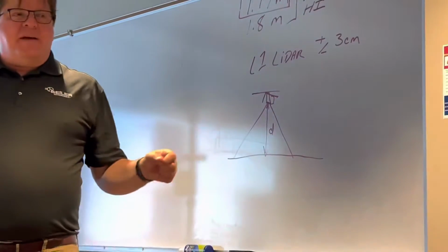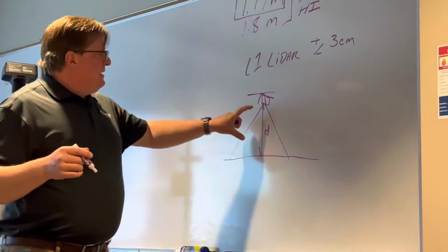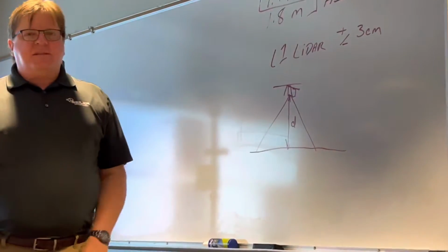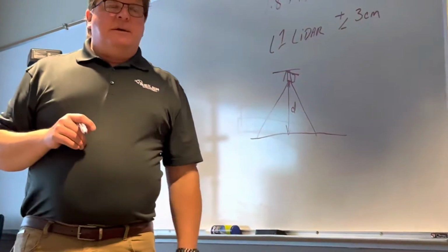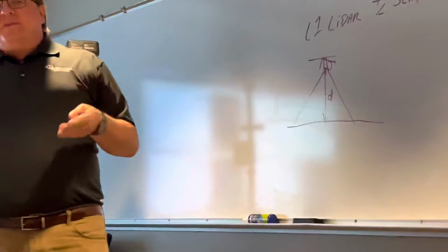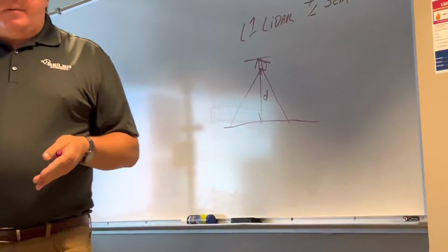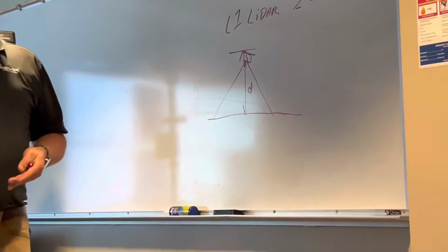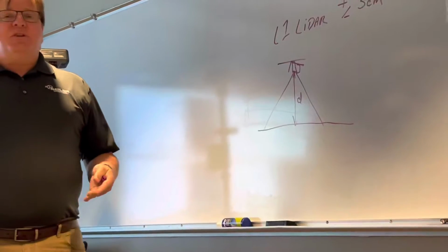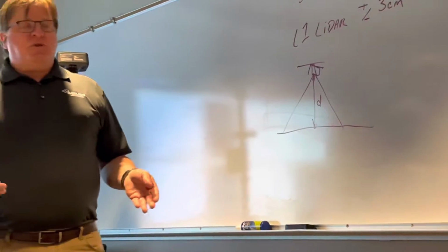And that focal length with the distance, there's a ratio of the focal length to distance that calculates what's called the ground sampling distance. Basically, the ground sampling distance is the representative size of a pixel on a photo, okay? So your final model accuracy is determined by the ground sampling distance, or GSD.